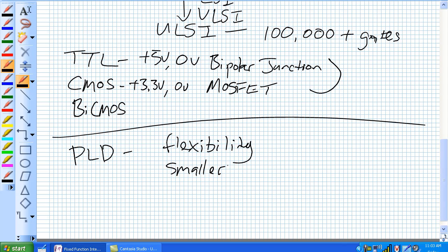You know, another advantage of the programmable logic device is, remember our previous discussion about printed circuit boards, where you've got all these interconnections between a number of fixed function integrated circuits? Well, with a PLD, you're simplifying your printed circuit board in the fact that you have one device, which may require only a couple inputs and a couple outputs.